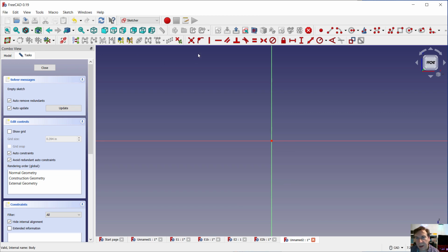Now to begin with, we're going to draw with the polyline right here. I'm sorry, polyline, not polygon line. Go ahead and select that. Now infer a bit of a distance to the left of the origin, which is at the center of the crosshairs, but align yourself to that line that you see. It's highlighting right now, mine yellow. Go ahead and click when you have that.